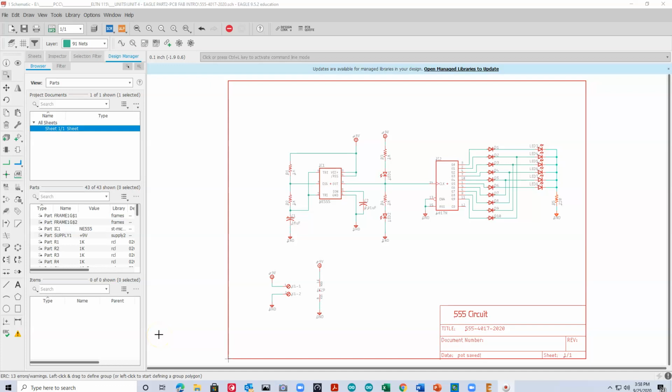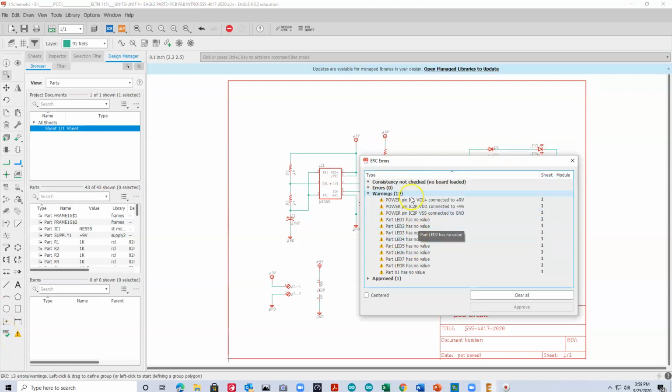In this video, I'm going to go over how the board program works, how to launch that based on a schematic. But first I want to take a look at the schematic that we have here. Your schematic should look pretty similar to what is shown here. There may be a couple of minor differences, the way things are placed or located, but overall the schematic should look generally the same. Now I'm going to run the ERC and see what errors we end up with.